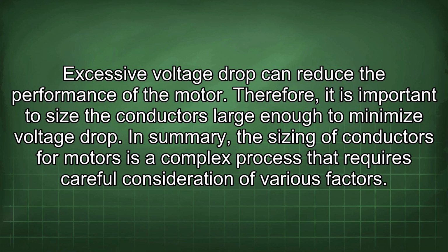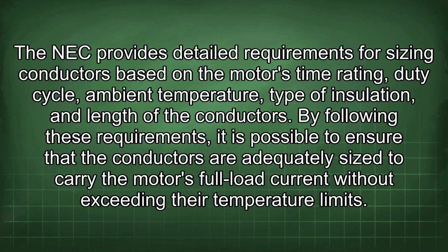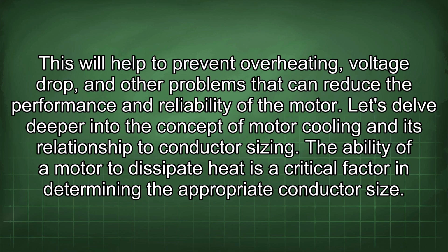In summary, the sizing of conductors for motors is a complex process that requires careful consideration of various factors. The NEC provides detailed requirements for sizing conductors based on the motor's time rating, duty cycle, ambient temperature, type of insulation, and length of the conductors. By following these requirements, it is possible to ensure that the conductors are adequately sized to carry the motor's full load current without exceeding their temperature limits. This will help to prevent overheating, voltage drop, and other problems that can reduce the performance and reliability of the motor.